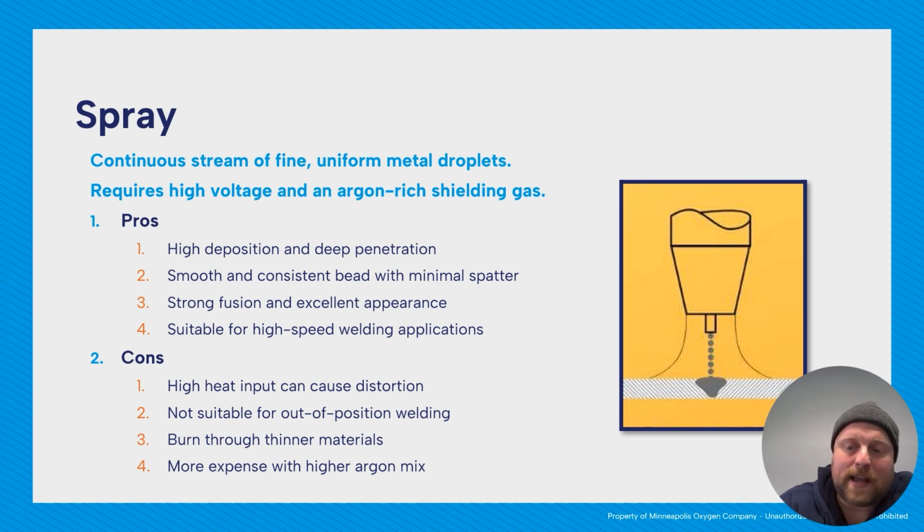So when I was saying previously with globular how some people think that they might be in spray but they're not, what'll happen is people will be in short circuit and they're like, okay, to go to spray, I'm going to crank up my wire feed speed and crank up my voltage.